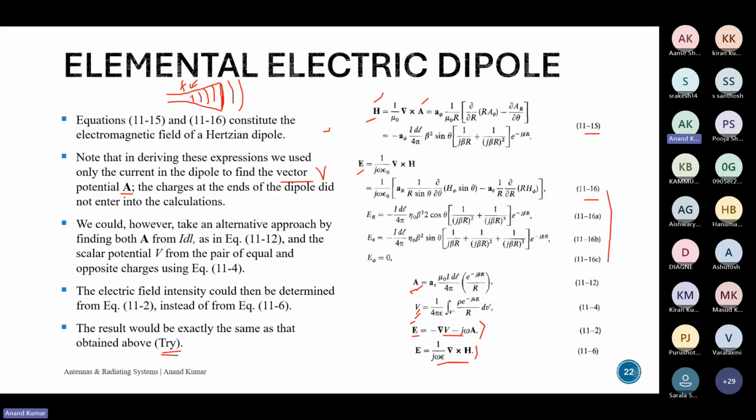But yeah, so Hanumant, is it? Yeah. So you can look into Vivaldi antennas and horn antennas. Maybe you can get an idea of broadband matching. If you are not concerned about the size of the antenna. If that is a concern, then you'll have to look into more papers on that.